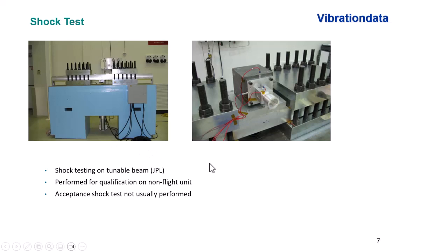So what the test conductor would do, prior to the test, is the actual component would not be mounted on the cube, rather maybe a mass simulator would be mounted. And then the test conductor is going to do some trial and error experimentation, determining what set of parameters are needed to get the required level for the specification. So this is a common way. There's actually a commercial version of this that's out there. And then there are yet other ways of doing mechanical shock testing. We'll cover those later on.